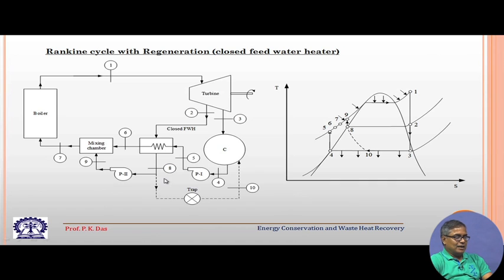But then the drawback of this process is that this condensate is at a high temperature. That high temperature condensate I am taking again to the condenser, and it has to be cooled back, and then some amount of energy wastage or inefficient use of energy is there.